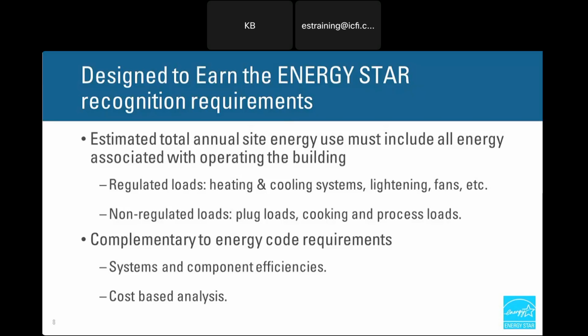I get the question many times, well, if I get an Energy Star score or if I'm 30% better than code, what's my Energy Star score? Well, my answer is always, it depends, because what I have drawn up and the strategies I chose and how I chose to evaluate those percent better than code, which is a cost-based analysis, is different from the next person in the room. So therefore, your 30% better than code may be different than my 30% better than code because I use different strategies and technologies. Now, of course, if we're in different regions and you're doing cost-based, you know it's going to change then. But let's just say we're both in Colorado and we're doing the same design, it may be different.